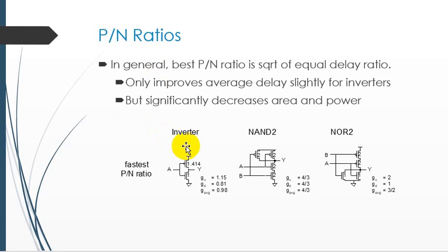The PMOS transistors in the unskewed gate are enormous in order to provide equal rise delay. They contribute input capacitance for both transitions while only helping the rising delay. By accepting a slower rise delay, the PMOS transistors can be downsized to reduce the input capacitance and average delay significantly.